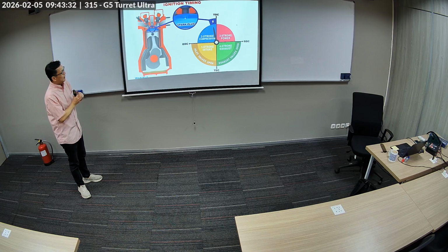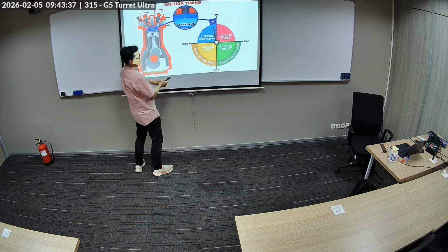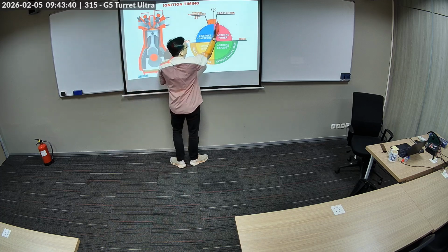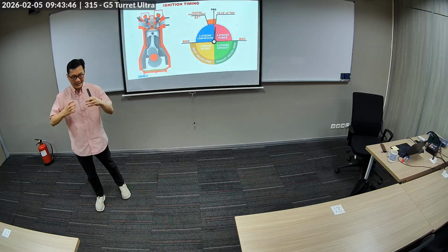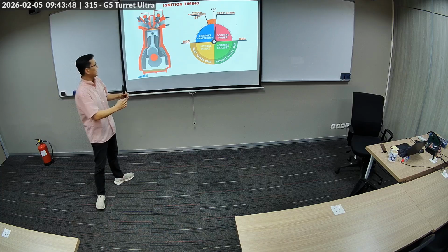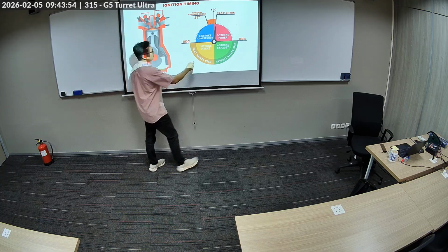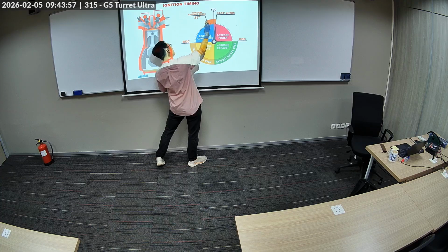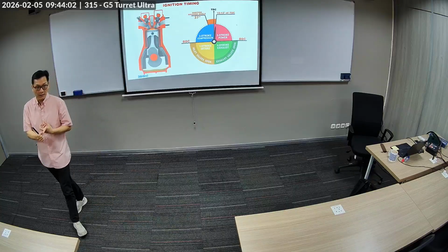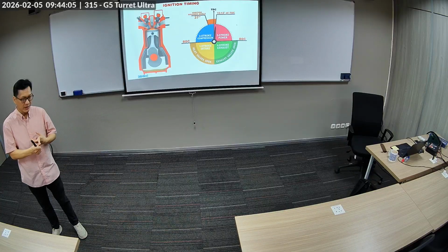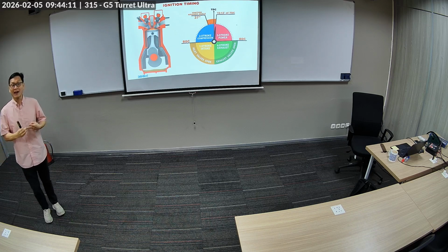Spark plugs, they are the ones that spark the flame. Okay. So this is where you want the maximum pressure to be, where the combustion is complete, and then it starts hitting the piston and creates power. But in order to create it here, you have to start early, right? And ignition angle is really one of the most critical parts in tuning. So fuel ratio, yes, but what then optimizes your tune is actually the ignition angle.